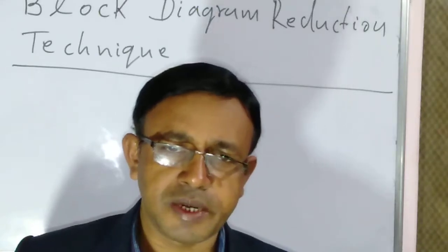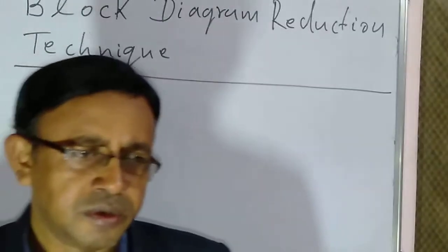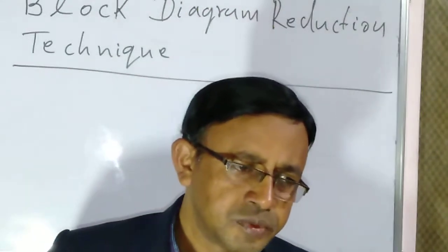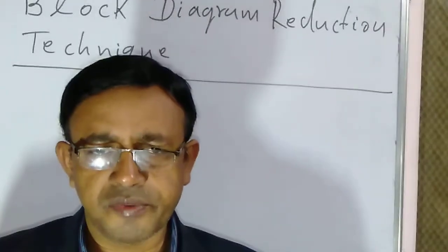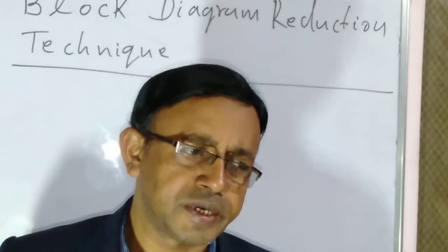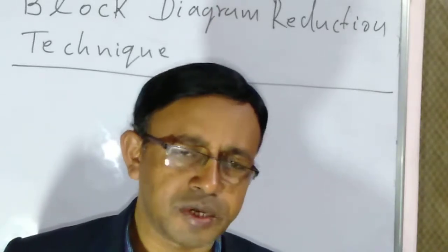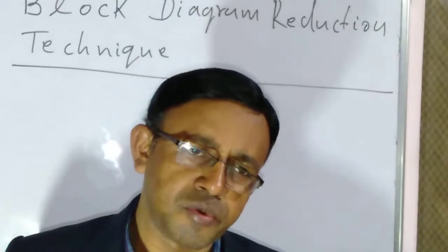But for an analog multimeter, the input impedance is low, therefore it has more loading effect. It means when we connect the analog multimeter to any circuit, it will load the circuit.